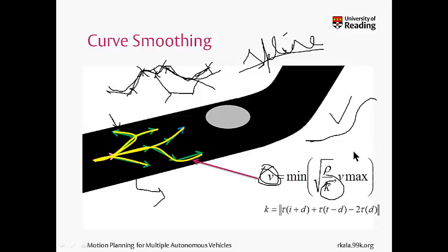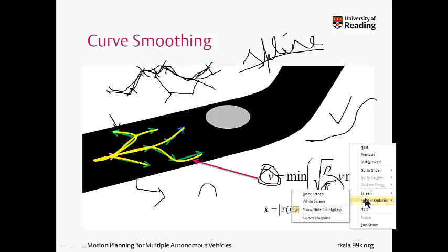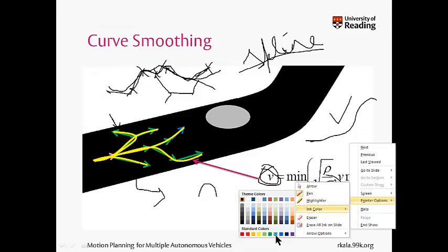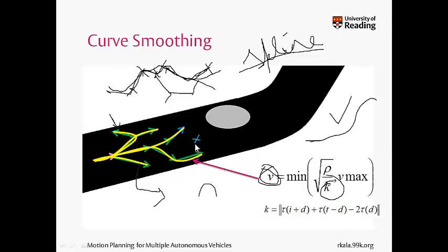I accept it. If the speed happens to be lower, that means a very sharp curve exists in the RRT. As for example, let's say that I generate a new curve like this, and the extension happens like this, and the smoothened RRT is like this. Now this is a very sharp turn. The velocity will come out to be much lower than the operating speed of the vehicle, and I'll not admit this solution. I'll say that this node cannot be added. So this is an additional check that I have produced of curve smoothness and velocity check, that every addition should produce a smooth curve which is traceable by the vehicle.